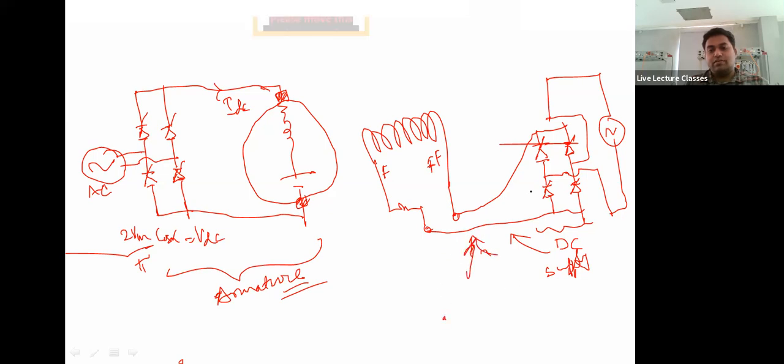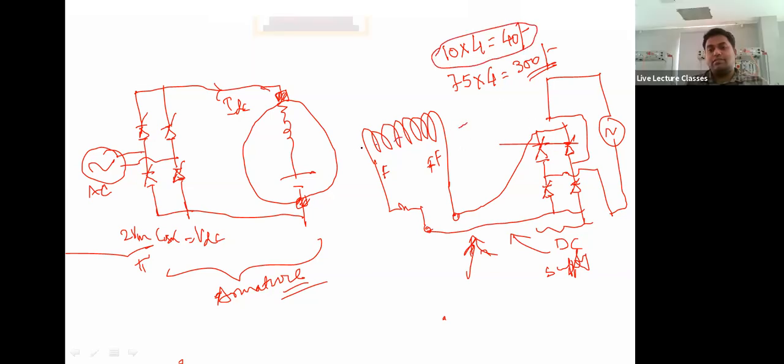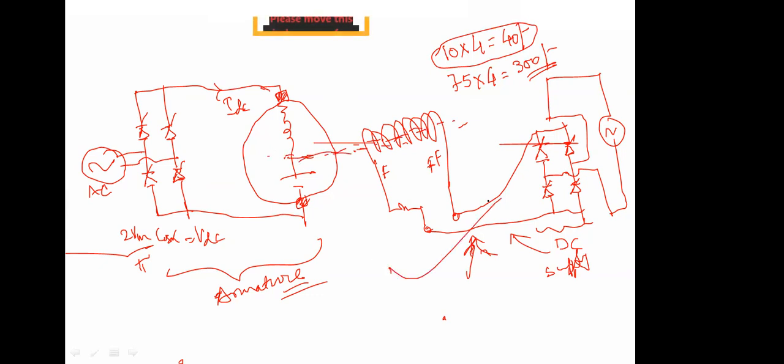See, what is the cost of a diode? The cost of a diode would be around 10 rupees per unit, so four diodes are 40 rupees. And the cost of a thyristor? A minimum thyristor locally would be around 75 rupees, times 4 would be 300 rupees. So which one would be the cheaper option? Diodes. So just go for four uncontrolled diodes and supply this with the full amount of voltage. It is done for you. I myself have done this several times, so it is good.